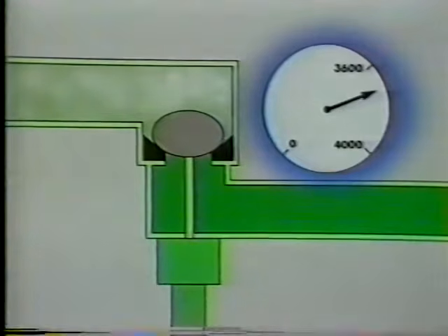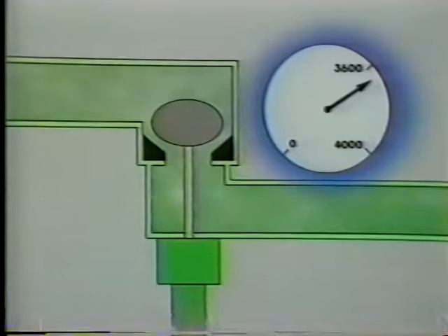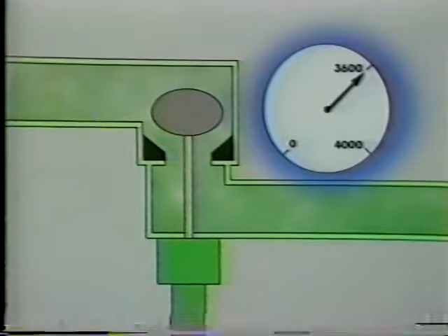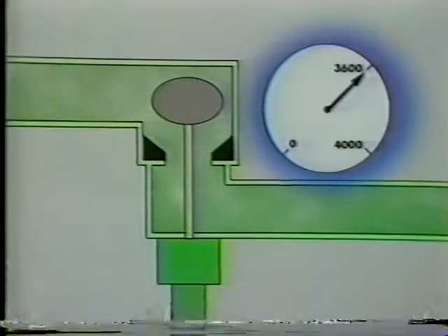However, once the turbine slows down to a safe speed, the intercept valves could gradually reopen and let the trapped steam out of the reheater. Since intercept valves are regulating valves, the flow of trapped steam can be adjusted to control the turbine speed.